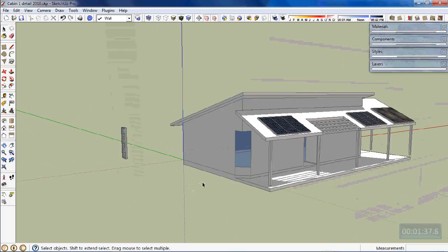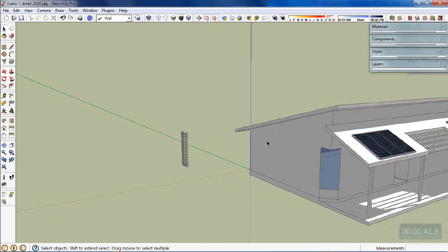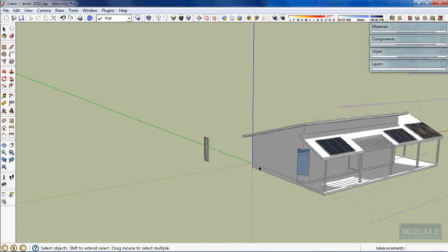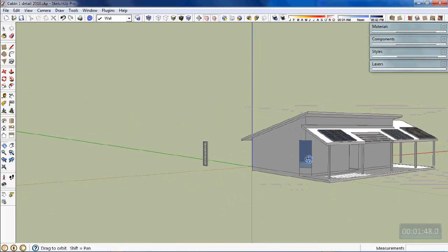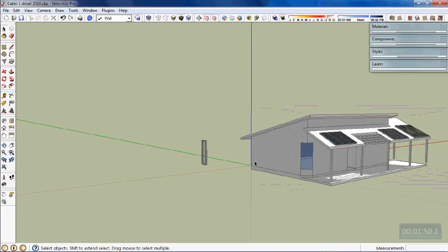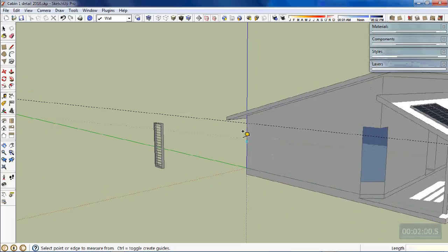Just as an example, I wanted to show you what you have to do to your model now to start populating windows through here. So if I wanted to put some louvers like that just at the back edge, just as an example here, and you can then decide where you want your windows to be. I'll do a 2100 high joinery line. I'll bring it back 600 off the corner. We size the window to be 600 wide,